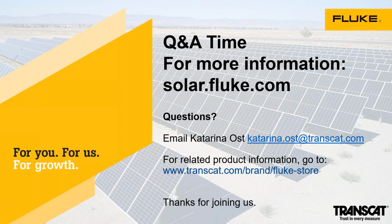Okay, we did get another one. Can you use the SMFT 1000 on 1500 volt utility scale systems? That's a great question. So the SMFT 1000 is rated for 1000 volts at 20 amps. You can use it on utility scale 1500 volt systems with some limitations.